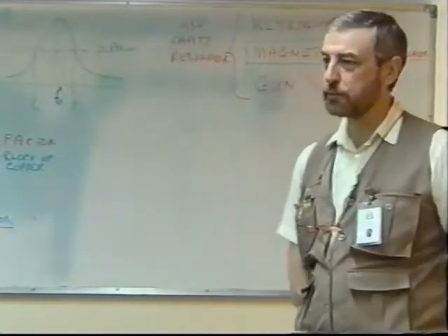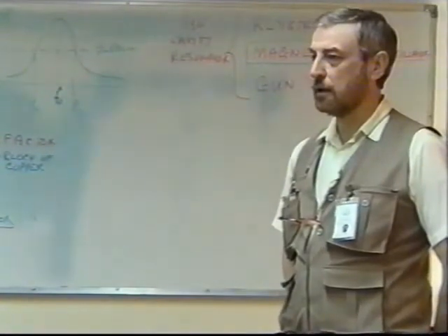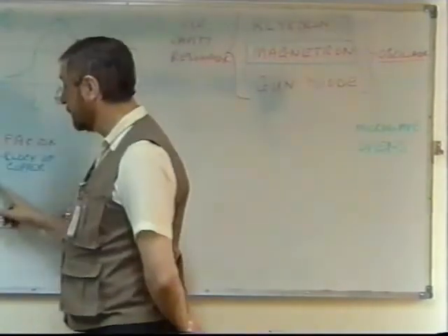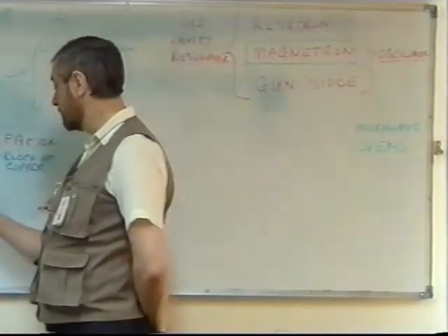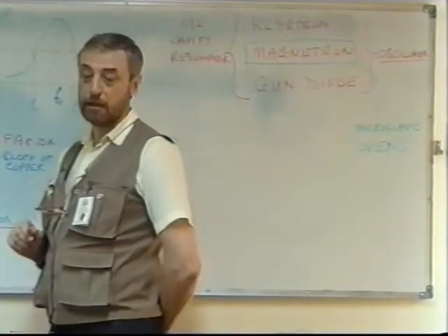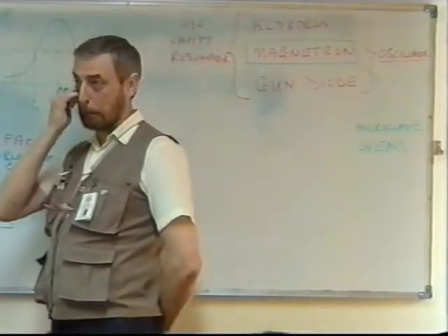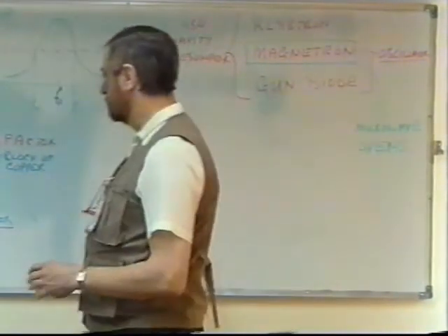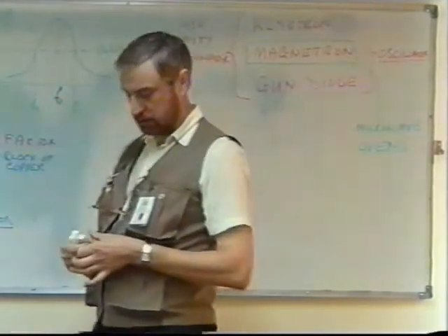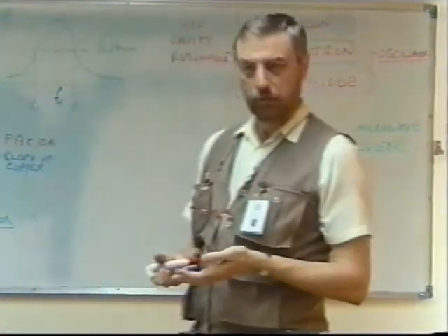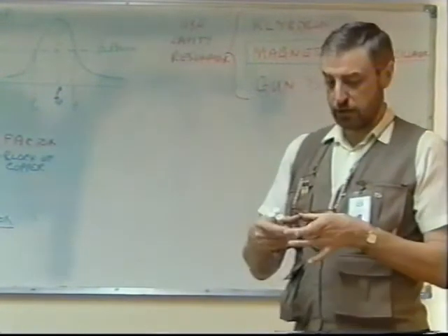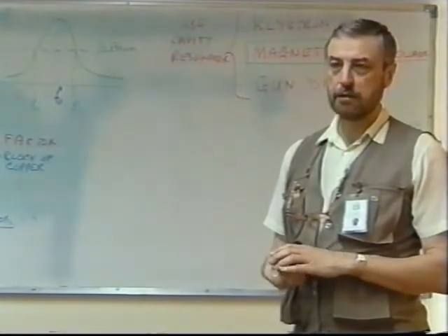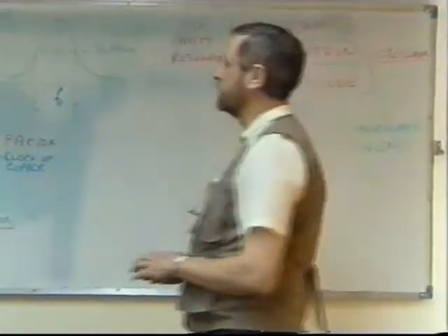To get a higher Q factor, make the cavity resonator bigger. Well, the reason why this has a very high Q factor is because the resistance is very, very small because it's drilled out of a solid block of copper. And that makes it a very high Q. Let's make it bigger. I'm not quite sure. I mean, they're not going to be that big. But don't forget, these holes here are very tiny, small little things. But you can always tell, they're reasonably heavy, even though it's a small block. It's quite heavy because it is a block of copper. It's not like a printed circuit board.